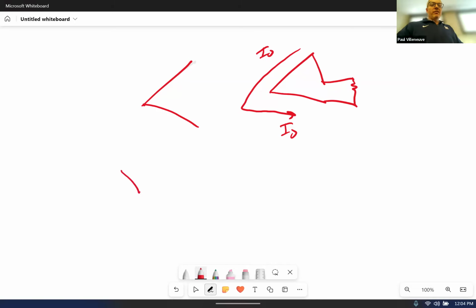But now everybody does it this way because you can calculate what I0 needs to be. The relays today, the devices are smart enough to tell you I0 is this. They'll actually do a calculation for you. Where back in the old days, you didn't have the calculation capability. So you had to do all these tricks to give you positive sequence current, negative sequence current, zero sequence current.